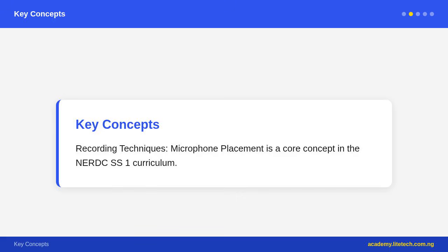A condenser microphone uses changes in electrical capacitance to generate the signal. It requires phantom power, typically 48 volts supplied by the mixing desk or audio interface. Condenser microphones have a more detailed, sensitive response and are generally preferred for studio recording of vocals, acoustic instruments, and nuanced sources. The Neumann U87 is considered the reference condenser vocal microphone, though there are excellent affordable options at a fraction of the price.